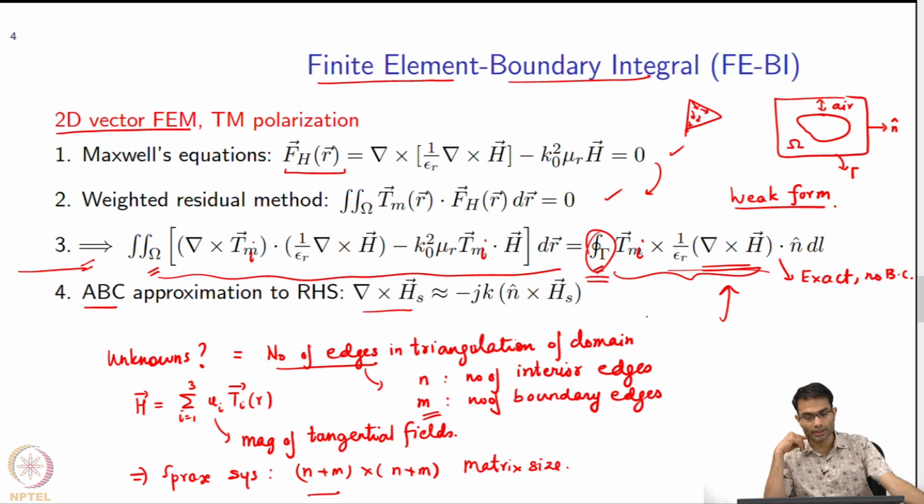No, so this is along the overall boundary. We had actually worked it out: when we write it for each element, these terms cancelled along the individual boundaries, and you were only left with the outermost boundary that did not cancel. At this point FEM has actually not come in. We had applied the divergence theorem to convert an area integral into a line integral, which is why the right hand side became a line integral. So this is true only on the boundary.